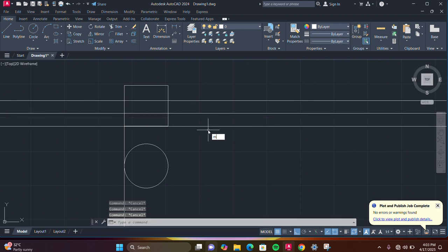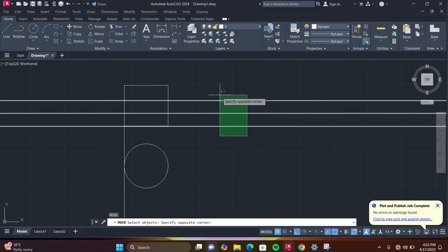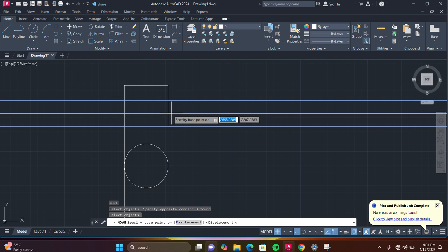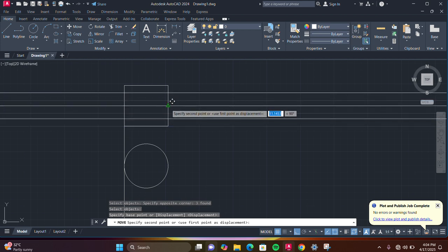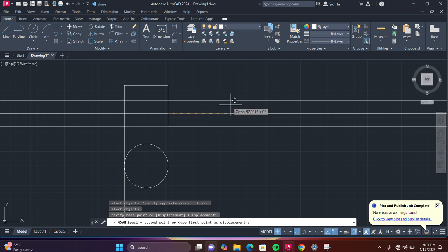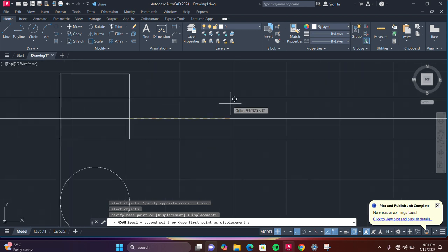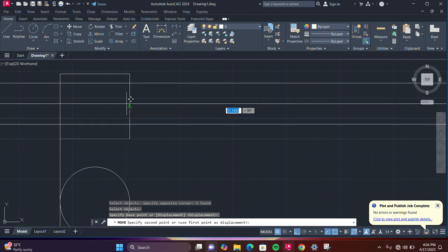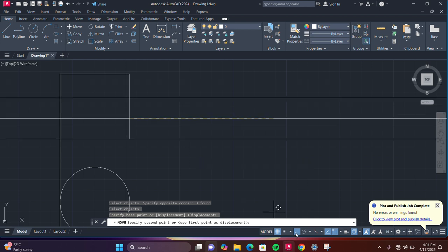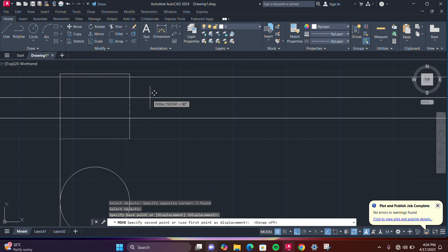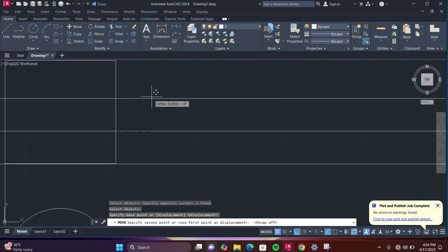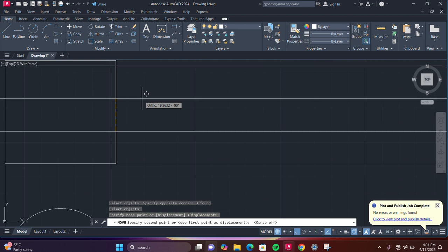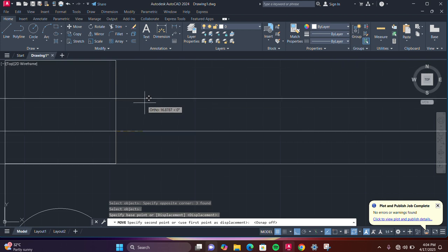So you can move it, M, enter. So there will be perfect intersection between the vertical and the horizontal. So you just move it, ensure it is. You can move it. So before moving it, you can remove your auto so that it will not be moving to points described by the auto. You can move it to a convenient place. So now let's move it like that.